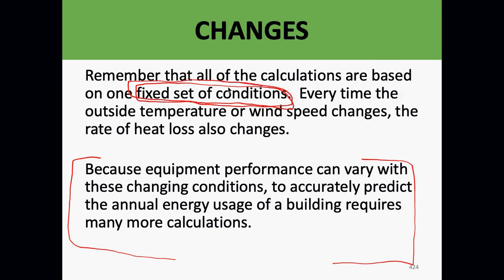Never use the average. If you say, in your own house, that the outside temperature never gets above 85 degrees for most of the year, and then all of a sudden you have a summer that's 95 degrees, like I think we're probably going into this summer, you're going to be very uncomfortable through the majority of the year. So be careful about this. Don't minimize your calculations just to save money on equipment costs or make a bid look better. It is not worth it.